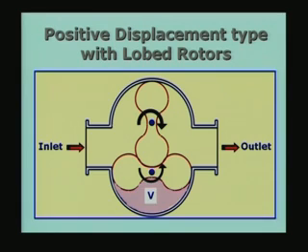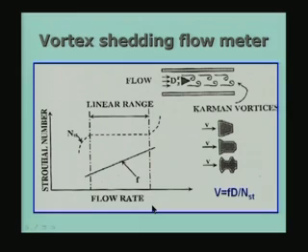instrumentation. In instruments where you want to deliver a certain amount of fluid per second, you can use a syringe pump. Of course, a syringe pump cannot operate continuously. When the piston position has gone from one extreme to the other, you will have to stop and refill the syringe and restart, and so on. There is also a positive displacement type of meter.